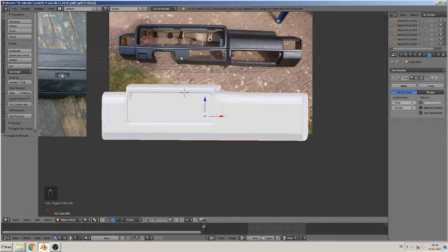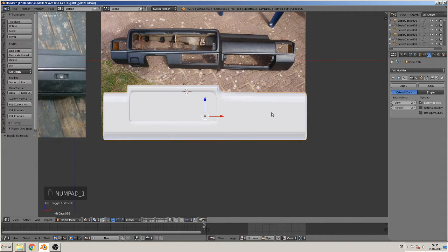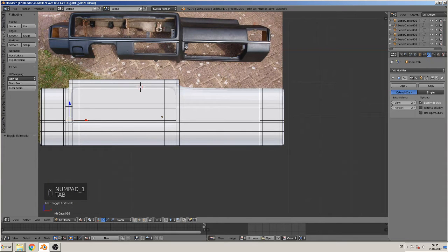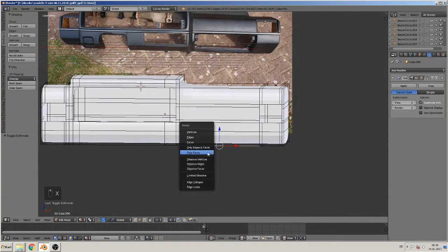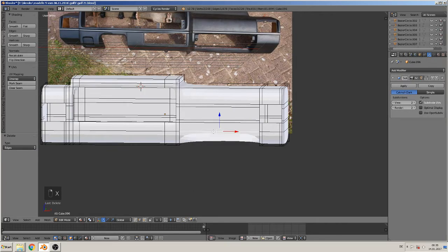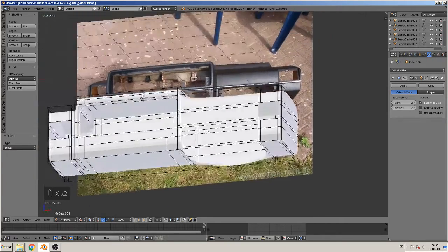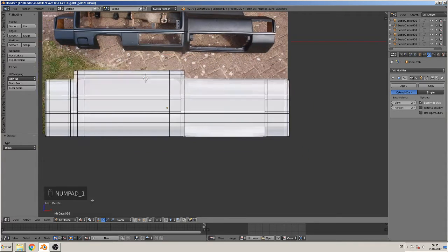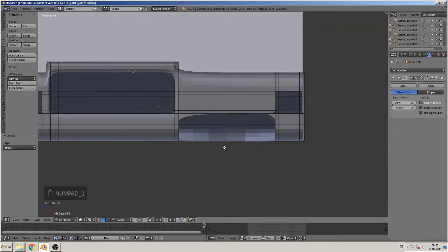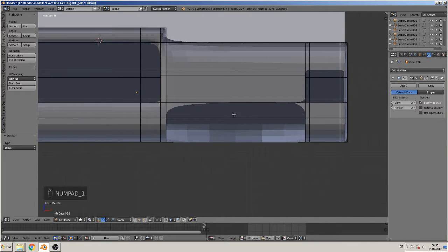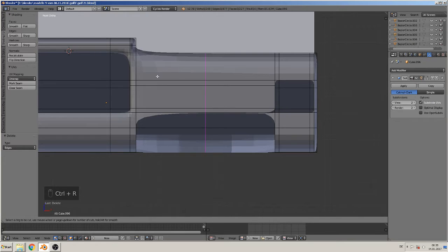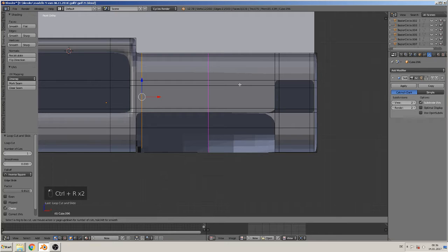Then we see we need another one down there and down here. So we go in this mode and we see that is this down part here. So we go here, edge selection, and delete the down edge, X, edge, X, edge. So we have that hole there. I show you that in solid mode again. And we now make the same as before. We go in and give them a loop to sharpen the roundness there, and another loop on this side.